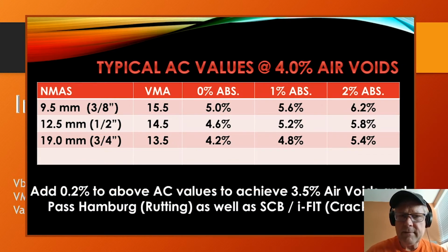These are typical asphalt content values that I think you're going to find with many, many mixtures throughout the U.S. If you have good aggregate gravity test protocol, and the water absorption of the products, then the total asphalt will be as shown in this table. It works for many aggregates around the nation, even the world. I have come to find out some of the southern, in particular Mississippi, they might not absorb 2/3 asphalt in 1% of water absorption, but maybe closer to 0.5% or slightly less. So their absorptive characteristics of their aggregates is just a little bit lower than what most of us are used to. And that again is, if you have 1% water absorption, you'll get 2/3 of that in AC, or if you have 2% water absorption, you'll get 4/3 or 1 1/3 absorption of AC. And that way you can make some good predictions when you look at mix designs.